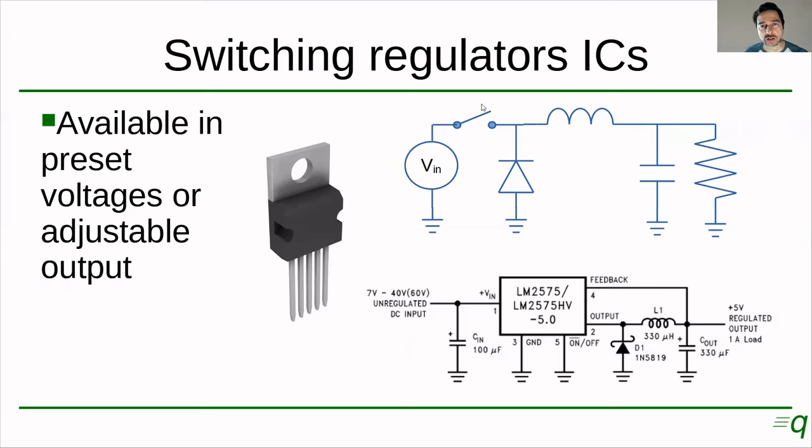Here we have a switch. The switch, of course, is one of the parts that is integrated into this circuit. So we have an input voltage here that gets connected to an external DC input, right? So that would be this part. Internally, we have a switch connecting the input voltage to the output that connects and disconnects several times per second. And we also have a ground connection here.